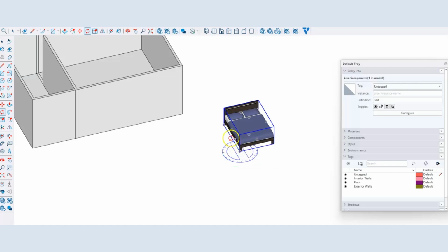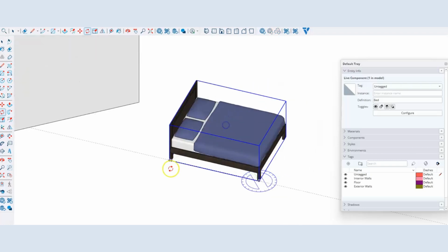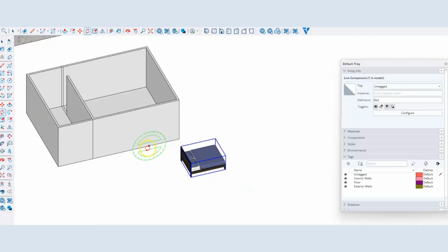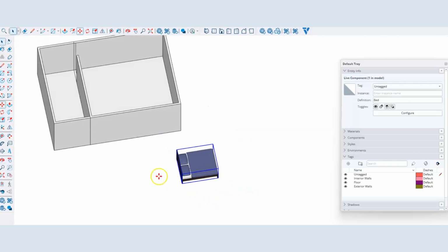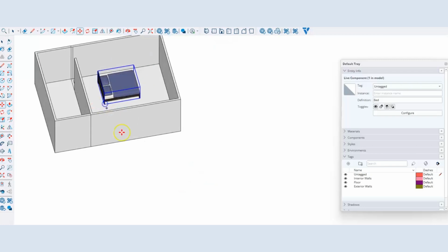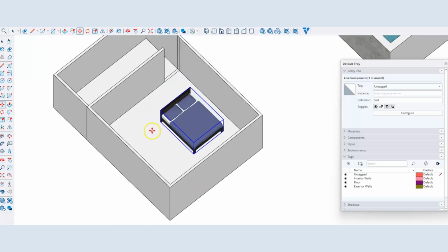One click, second click, and I can see in my measurement down the bottom right hand side, 90 degrees. So let's just say for the sake of this activity, that's what I wanted. Bring it in here. I just place it originally and then I can just move around and reposition it again. Here we go.